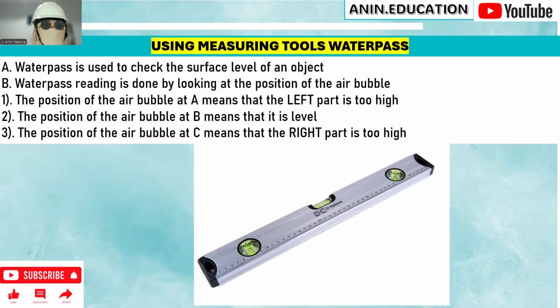Using the measurement tool waterpass. A waterpass is used to check the surface level of objects. And waterpass reading is done by looking at the position of the air bubble. One, the position of the air bubble at A means that the left part is too high. Two, the position of the air bubble at B means that it is level. And three, the position of the air bubble at C means that the right part is too high.